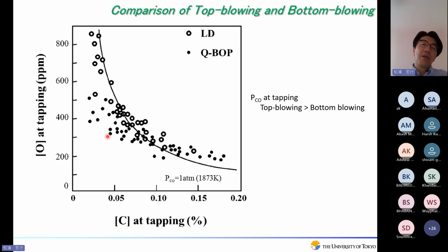As you know, the converter process decreases the carbon concentration, and in order to achieve that, you need to use oxygen gas. You can burn the carbon, but instead the oxygen content in molten steel inevitably increases like this. So at the end of the converter process, the oxygen content in molten steel would reach several hundred ppm. That is the source of the oxygen in molten steel.